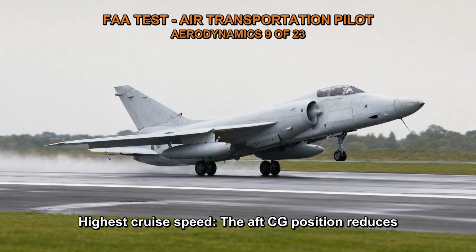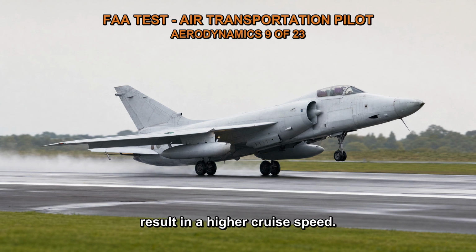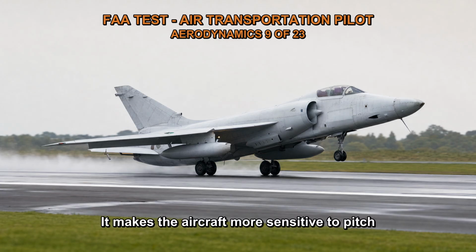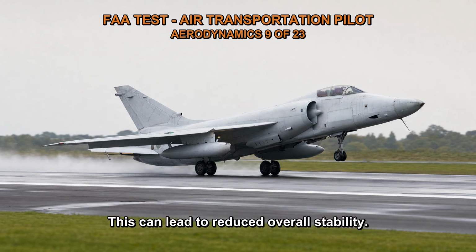Highest cruise speed. The aft CG position reduces drag by reducing the tail-down force, which can result in a higher cruise speed. It allows the aircraft to fly with a more streamlined configuration. Least stability. The aft CG position reduces the stability of the aircraft. It makes the aircraft more sensitive to pitch changes and less stable in maintaining a desired pitch attitude. This can lead to reduced overall stability.